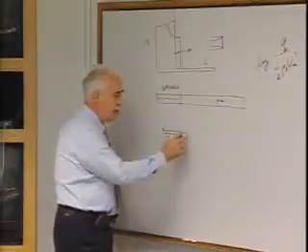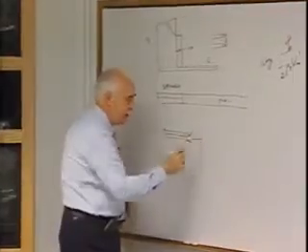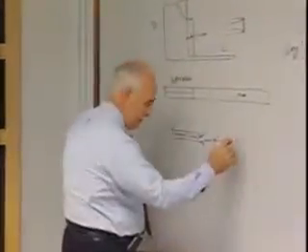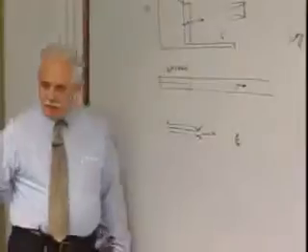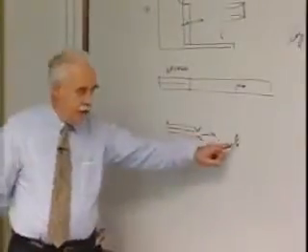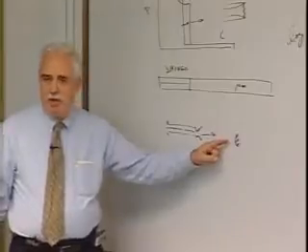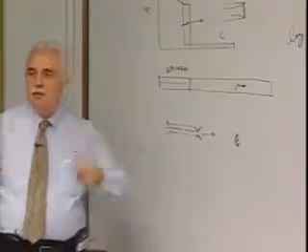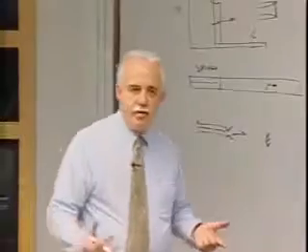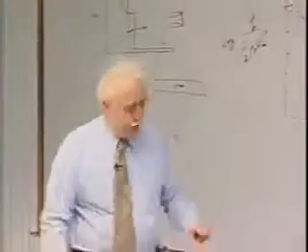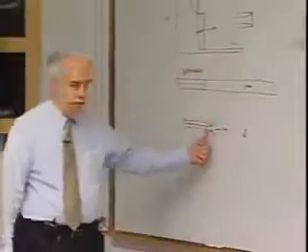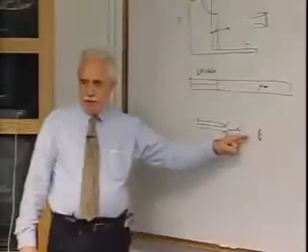Then you're expanding this and introducing a supersonic flow, and you test materials like the tiles or the ablator in as close to the environment as you can get on the ground. That is, for the times that are required. Entry times are like 20 minutes. So you need something that has the energy and runs for 20 minutes.